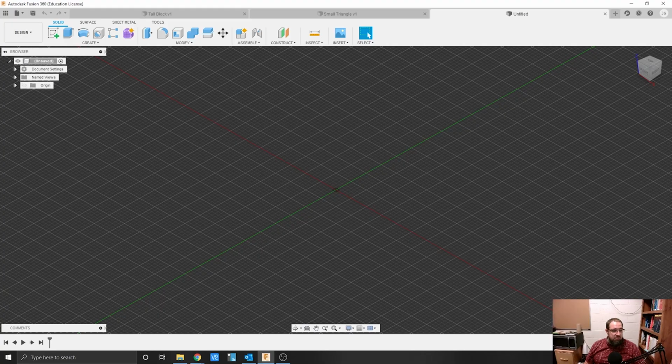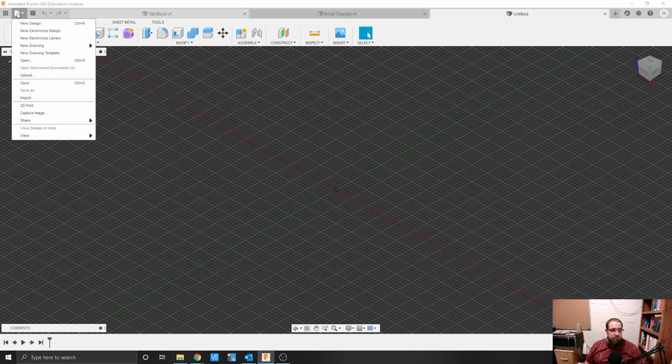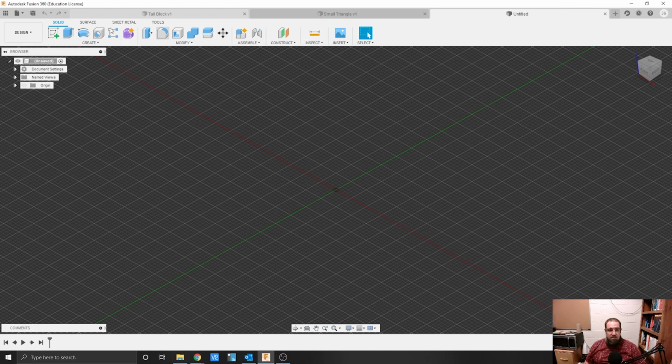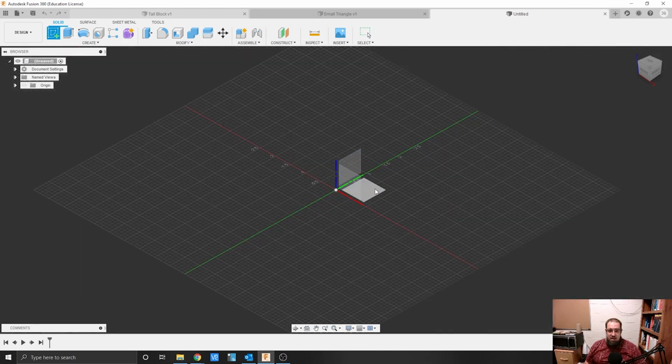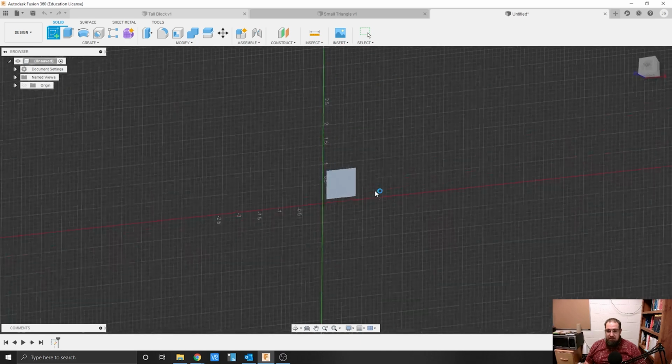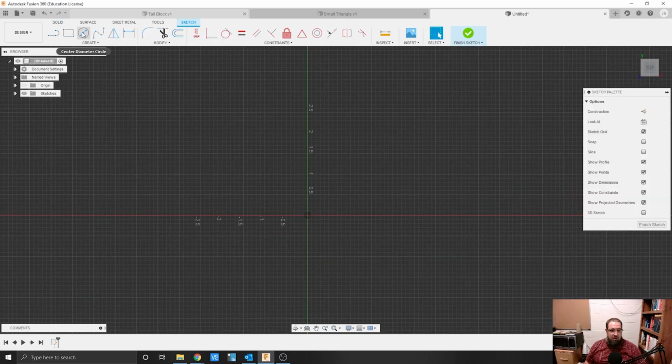And we're going to do our cylinder. And this is going to be our first 3 blocks. It's what gets turned in for our modeling software. Okay. So we're going to go to a sketch. And this one, I'm going to go back to that XY plane. Okay. Looking down on it. And we're going to create our circle.